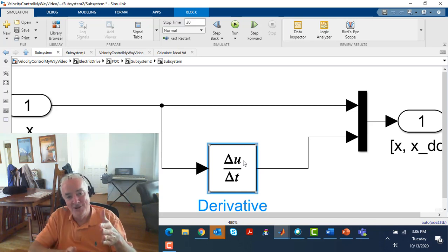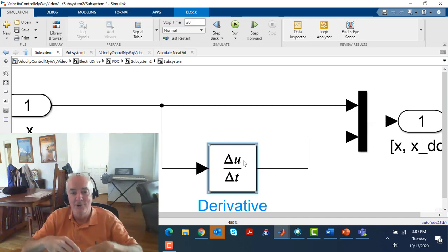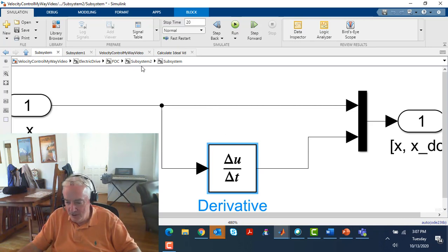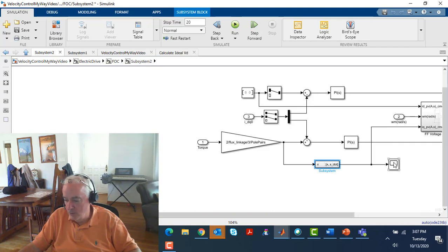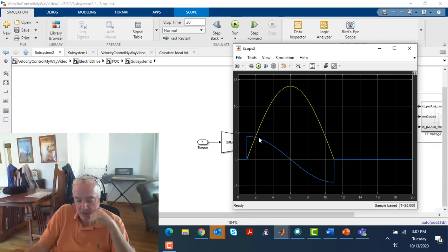like a step function or something like that into it, the problem is it wouldn't even calculate infinity. It either calculates some super big number, or calculates something that's not a number, and therefore, it's going to destroy whatever your controller's trying to do, right? But, in this example, and to show our tracking of this, things do work out pretty well because the quadrature current itself is finite, and so is its first derivative, right?